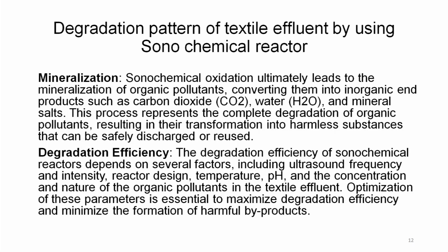Mineralization. Sonochemical oxidation ultimately leads to mineralization of organic pollutants, converting them into inorganic products such as carbon dioxide, water and mineral salts. This process represents the complete degradation of organic pollutants, resulting in their transformation into harmless substances that can be safely discharged or reused. So, you see that this is a very safe process and there is complete mineralization of the organic pollutant.